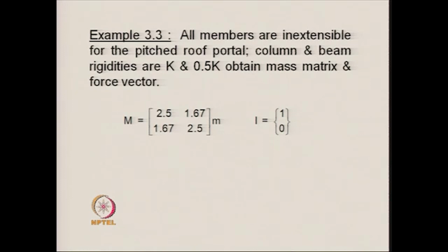Then we explained the equation of motion of a three-dimensional asymmetric frame with a rigid slab on top of it. The idea was to illustrate that in writing down the equation of motion, the mass matrix need not always be a diagonal mass matrix, as is thought in the case of point mass lumping. It was shown that depending upon the degrees of freedom chosen, the mass matrix could be a diagonal mass matrix, or also a fully populated or coupled mass matrix.